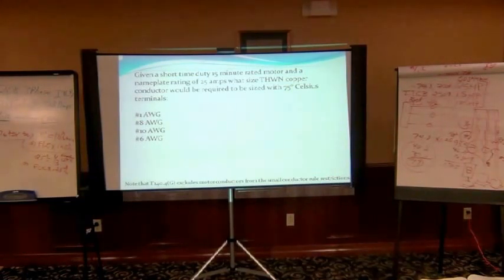Does a short time duty rating, 15-minute rating, have anything to do with this question? Yes, it does. It does apply when we're dealing with wire. We're under 430.22(E) since it's other than continuous duty. So all you need to know is 25 times what? For a short time duty, 15-minute rated, that's the first row. Was it the second column?